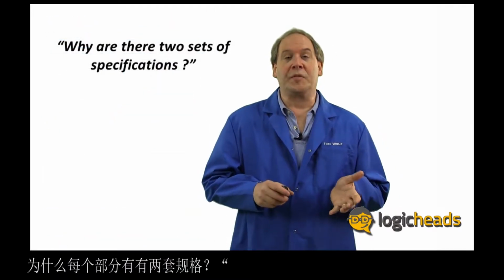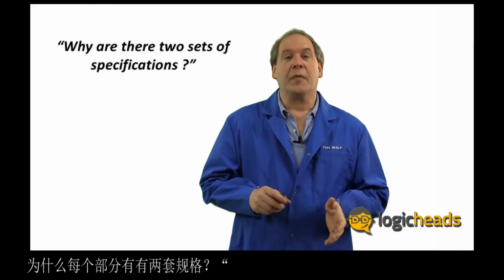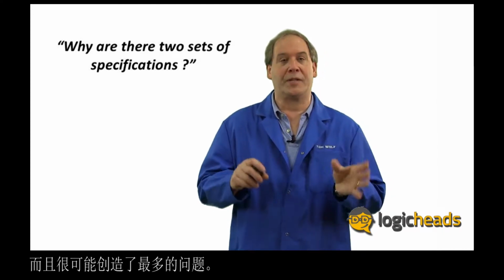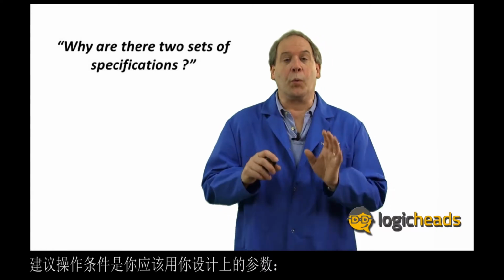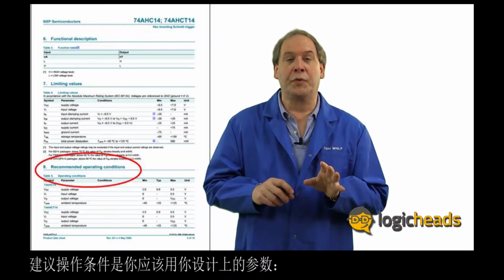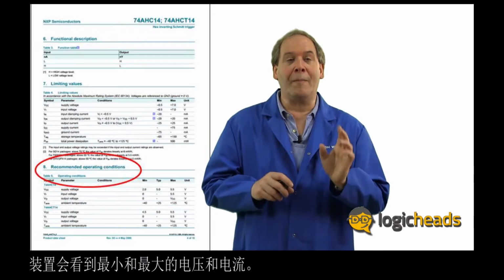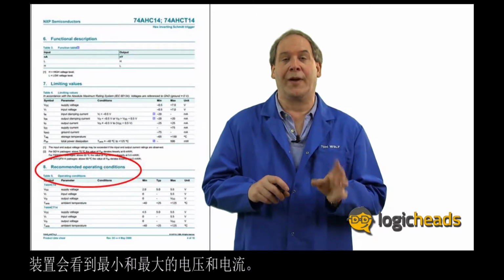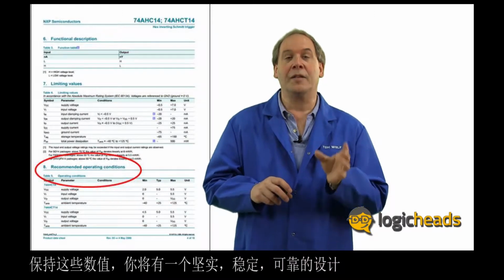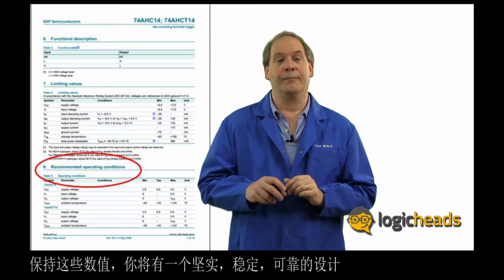Why are there 2 sets of specifications for each part? This is probably one of the most confusing parts of the entire data sheet and probably creates the most questions. The recommended operating conditions are the parameters that you should always use for your design. They give the minimum and maximum voltages and currents that the device should see. If you stay with these values, you will have a solid, stable, and reliable design.